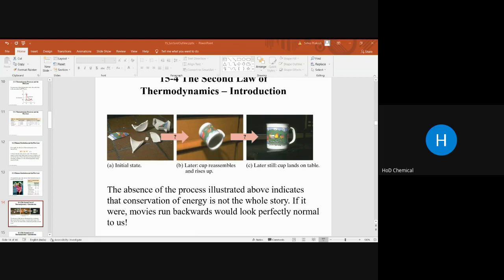It is highly idealized as it has no friction. Each leg of the cycle is reversible. So the Carnot cycle consists of isothermal expansion, adiabatic expansion, isothermal compression, and adiabatic compression. Examples are on the next slide.